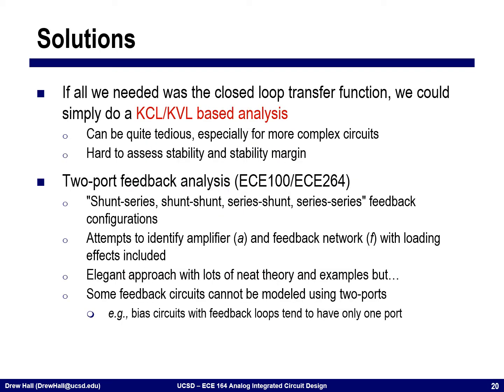All right, so coming back to ways of assessing the stability. If we just want the closed loop transfer function, we could always do KCL and KVL. And that's essentially what we resorted to earlier when we encountered that inverting amplifier. That circuit was really simple. As we start to look at more complicated circuits, this can get really tedious.